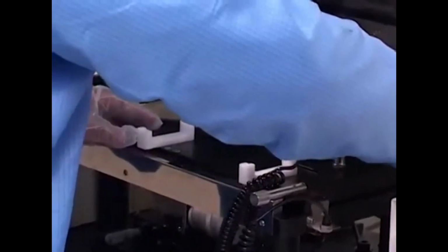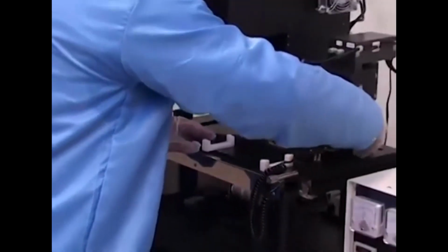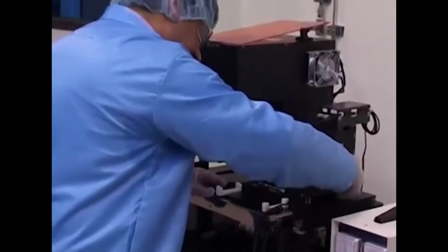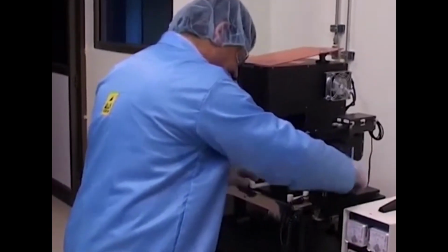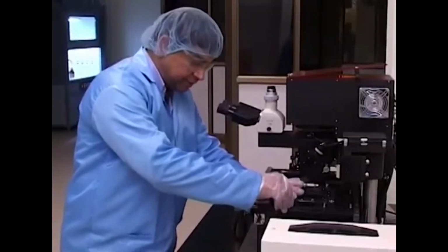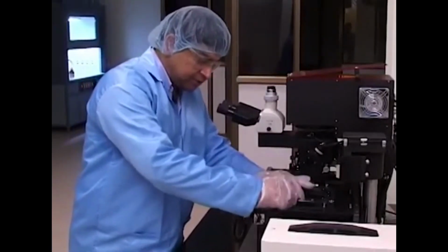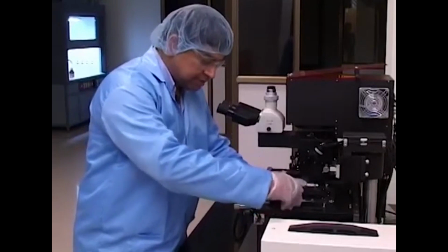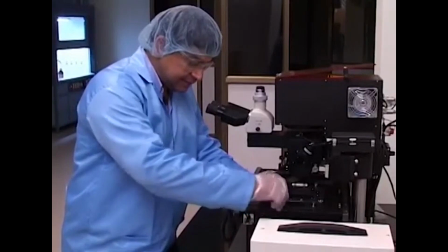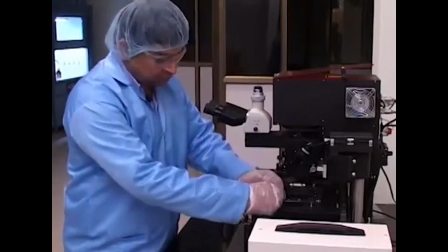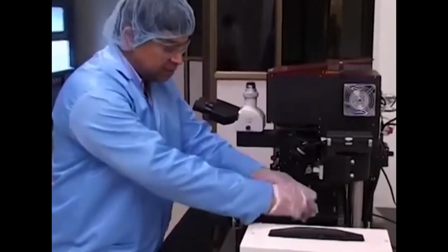You actually try to align them with the bolt heads which are there on the top of the mask holder, and essentially you can now use the locking mechanism to ensure that they firmly get locked over the wafer surface. So after mounting this properly, we need to bolt it firmly. We are going to use these set of screw heads to ensure that there is a good contact between the holder and it grips really well on the surface.